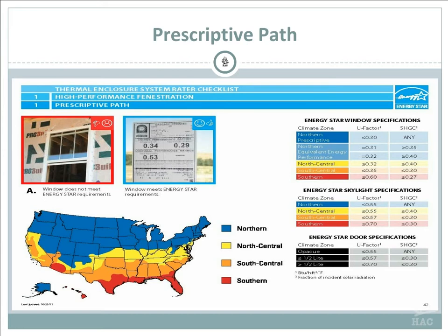The U value has an inverse relationship to the R value. So for example, a building material with an R value of R11 converts to a U value of 0.09. That's 1 over R, or 1 over 11, equals 0.09. Very confusing, but it's just the inversion of an R value to a U value.